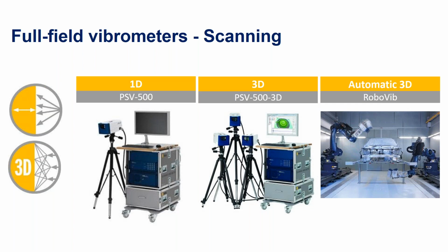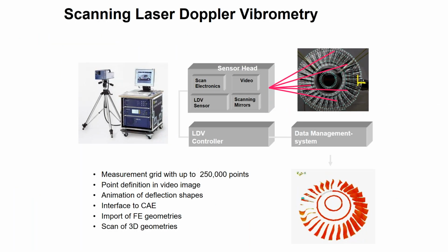It's a little bit more sophisticated because it has 3 lasers, but the idea is perhaps for modeling, you might want to use a 3D vibrometer because you want to measure in all 3 directions, vibration in the X, Y, and Z directions. And I think Bill has an example on that also coming up that we did on a tube for 3D vibration.